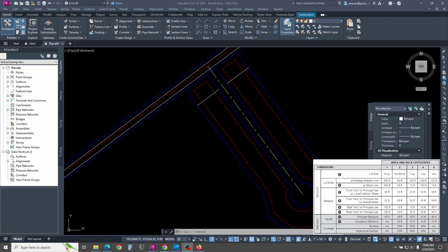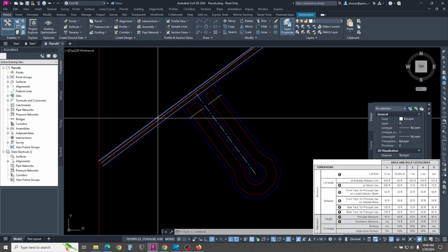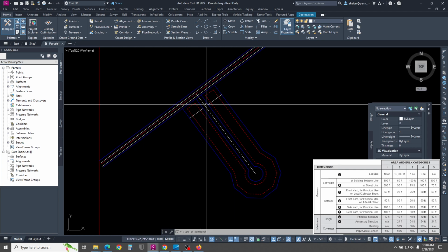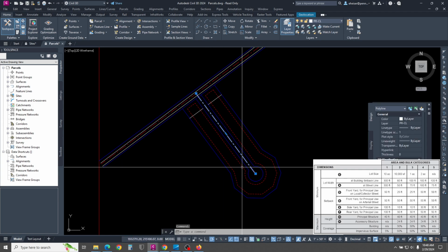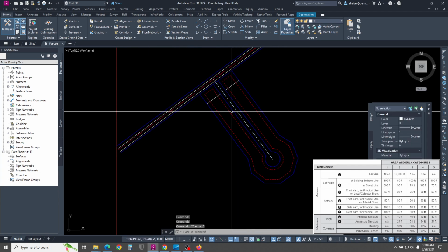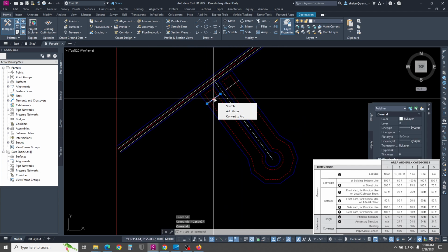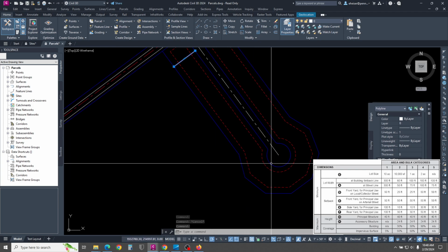So you should be able to see my CAD screen here, and I put the table down in the corner so you guys can reference where I'm getting the numbers that I'm going to type in. But whenever you start, I have just an existing road running along here, and I just drew a polyline for my center line. I offset it, threw a cul-de-sac bulb on it, and then I offset that back and took the arc out from the outside.